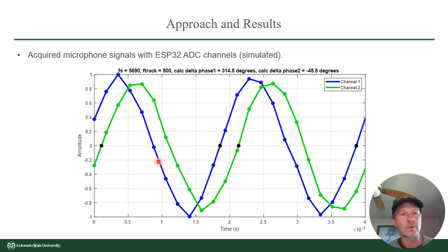And so that was a simple code path to determine that. So I calculated that it was 314.5 degrees, and so that's out of the physical realm of possibility for the acoustic array that I have set up. So if the phase shift is over a certain amount, I subtract 360 to get the real 45 degree phase shift. And yeah, there I point that out.